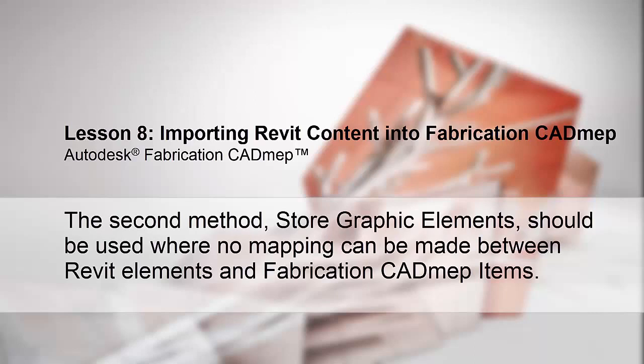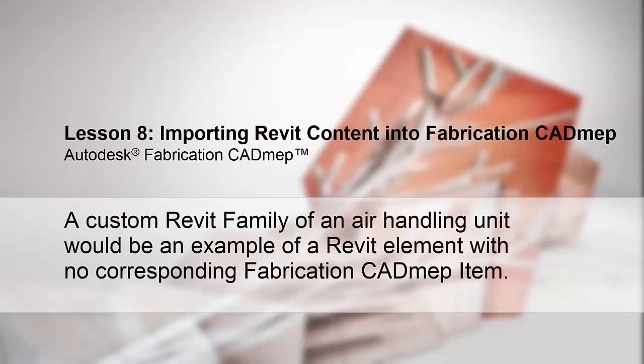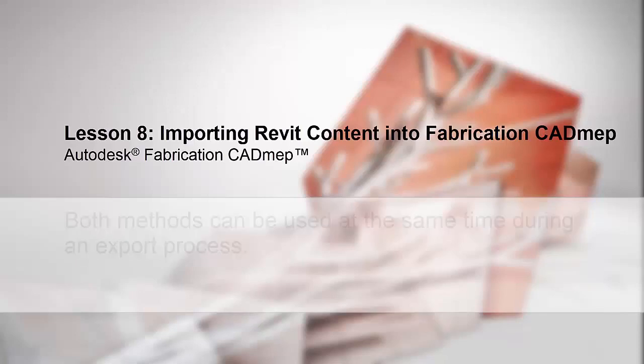The second method, Store Graphic Elements, should be used where no mapping can be made between Revit elements and CADmep items. A custom Revit family of an air handling unit would be an example of a Revit element with no corresponding CADmep item. The raw geometry of the exported Revit elements is used to create CADmep items with the connectors at the correct locations. Both methods can be used at the same time during an export process.